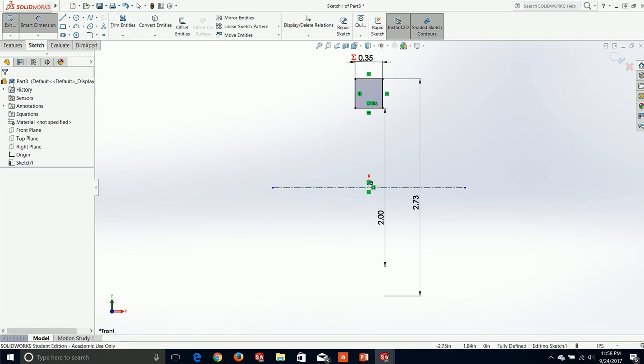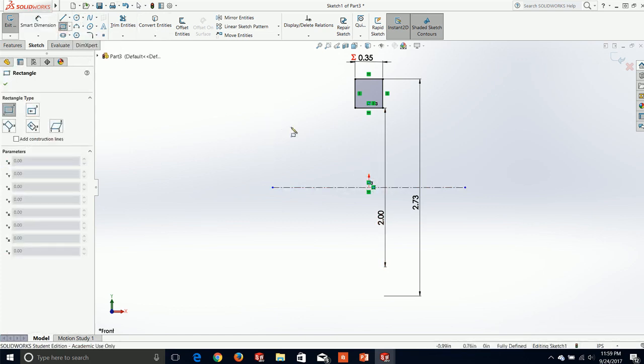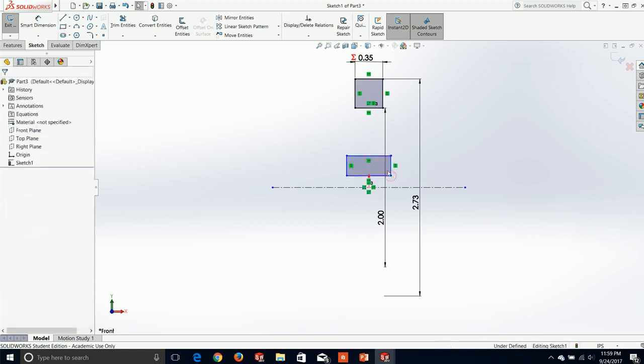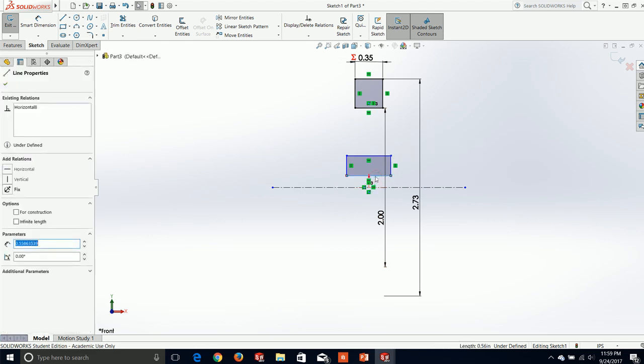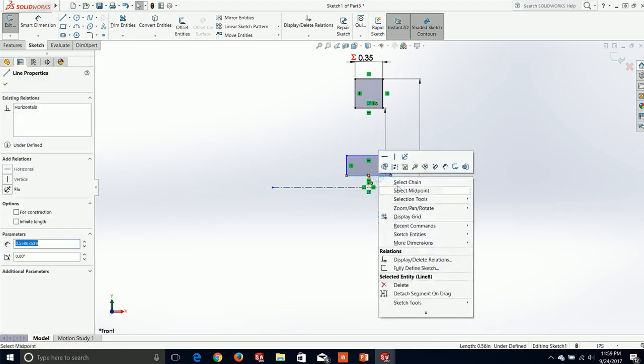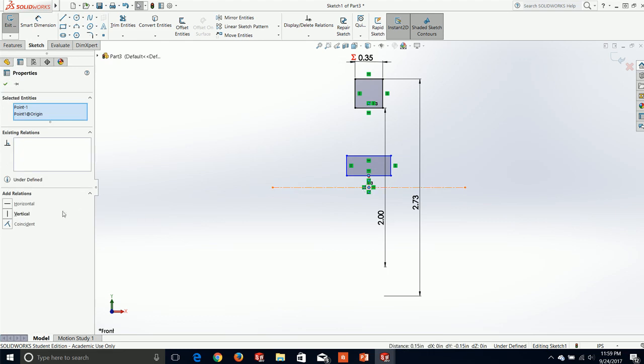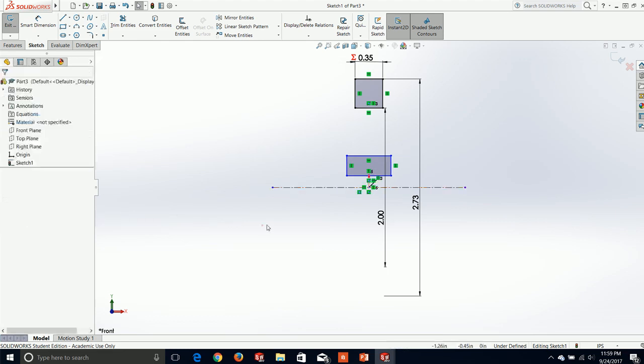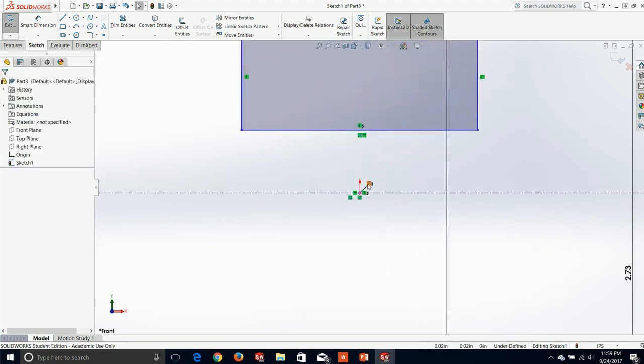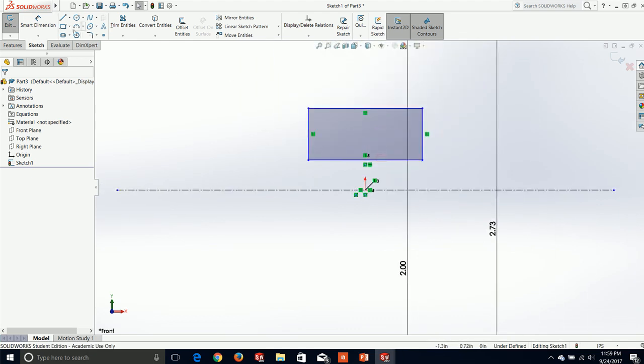But I can also go ahead and revolve this to create the outside of my wheel, and I can also create the internal part of the wheel as well. So I'm gonna kill 2 birds with 1 stone here, and do that. So I'll create another rectangle here. I'll grab the midpoint. Go vertical. And then I've got